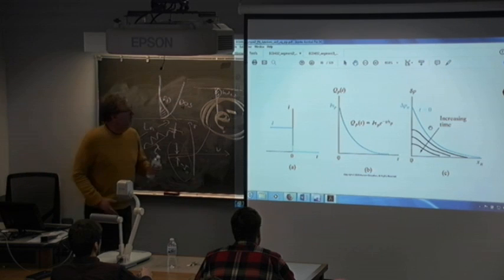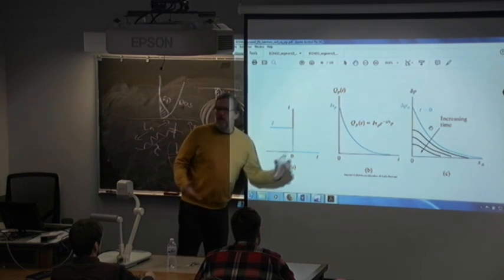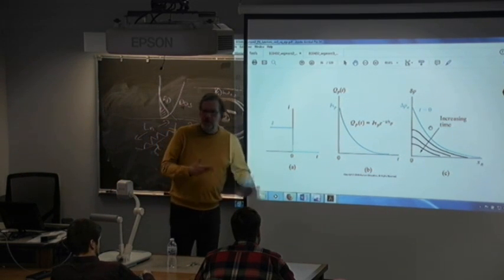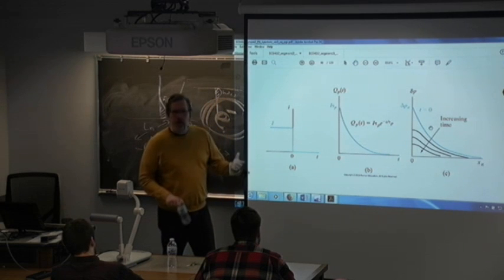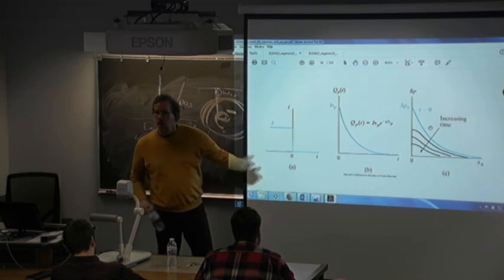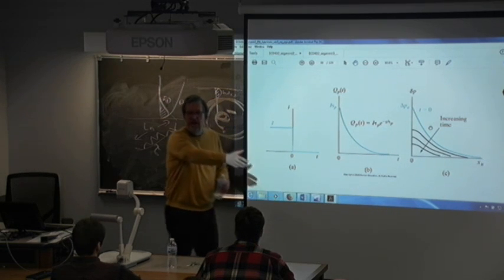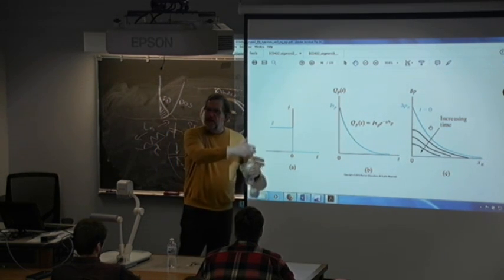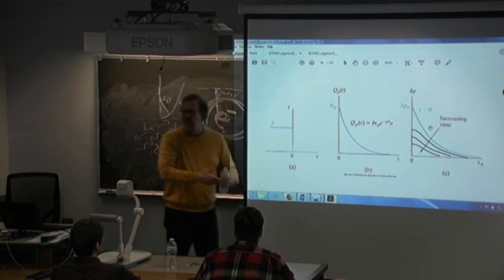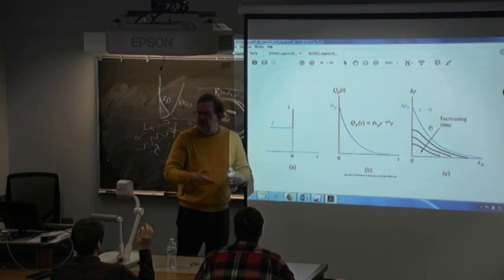It's like having a motor. You want to do some work on a motor and you unplug it from the wall. Do you go in and put your hand in right away? Probably not. You're probably going to wait a few minutes for the capacitors to discharge before the high voltage is safe enough to go in there.